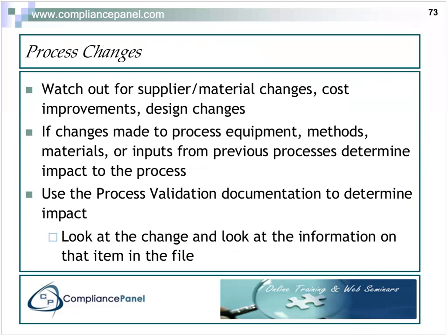Design changes of the product itself. Certainly we may have to make a process change as a result of that design change. Changes made to the process equipment. Somebody came along and put the latest software revision in a numerically controlled piece of equipment. What's going to be the result of that software change? Do we have to go back and revalidate the process because of that? That's a question we need to ask and make sure that it doesn't affect the product.